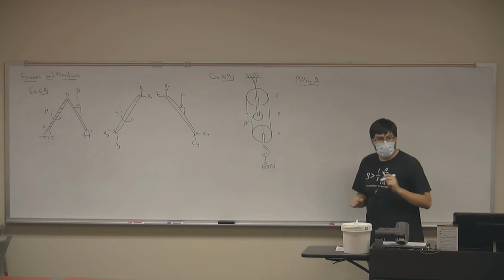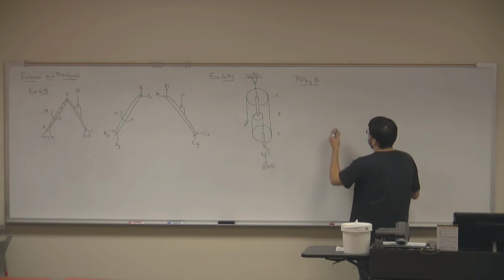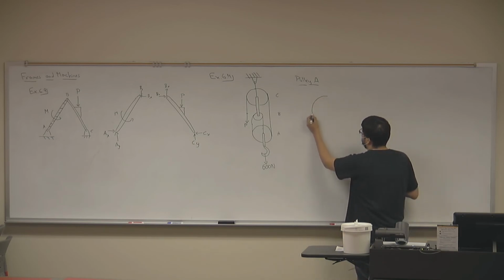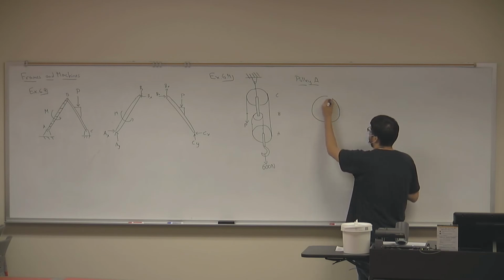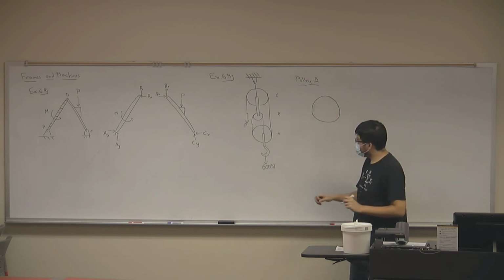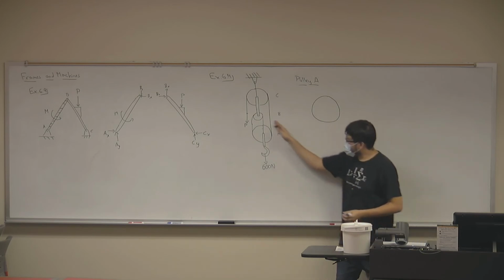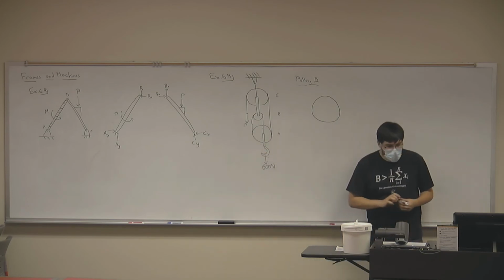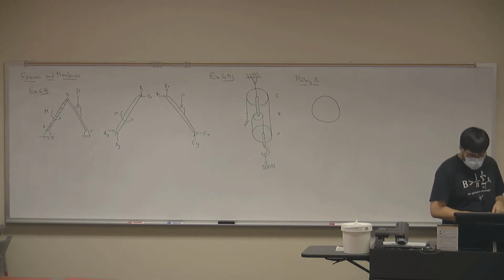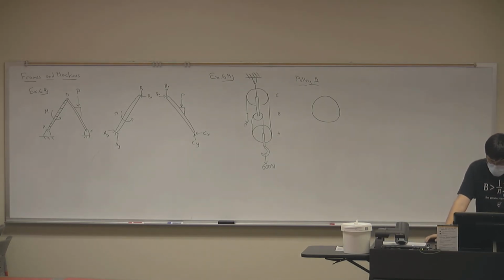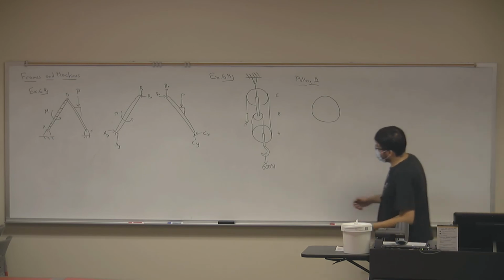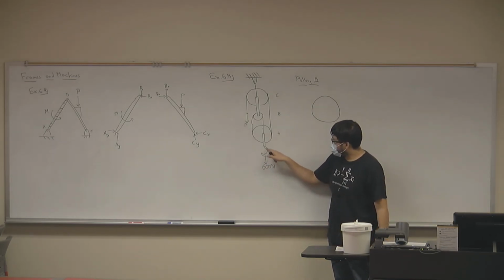And let's draw a free body diagram about that pulley. Let's neglect the actual weight of the pulley, so the only force that we're counteracting is not the weight, it's just the 600 Newton force. So if this is my pulley A, look at this pulley and think, what forces is this pulley experiencing? Obviously it's being pulled down 600 newtons. Notice that the 600 newtons is pulling on a hook that's connected to the center of the pulley.